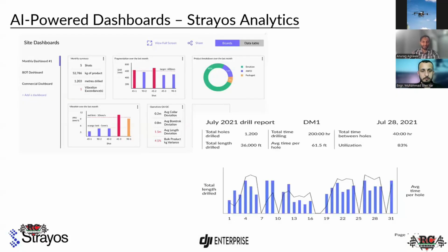After having all the input design and output design, you can visualize it in the dashboard for further analytics. Why is this analytics very important? Because currently we are only measuring the input design parameters. We don't have the output design parameters. We are just monitoring or writing the powder factor value, and we don't have any fragment size values. That's why we are not correlating them with the input design parameters.